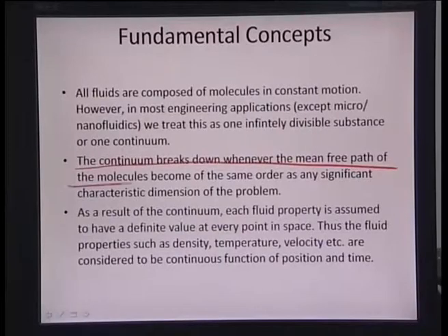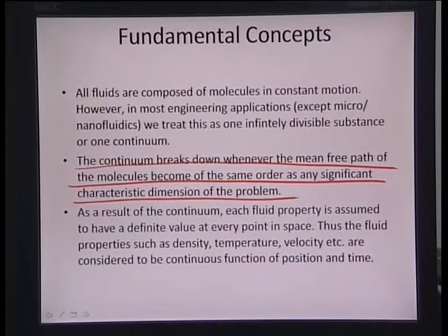So the continuum breaks down whenever the mean free path of the molecules becomes of the same order as any significant characteristic dimension of the problem. So if we are considering the volume element to be too small in comparison to the mean free path of an individual molecule, the probability of the continuum breaking down is greater.